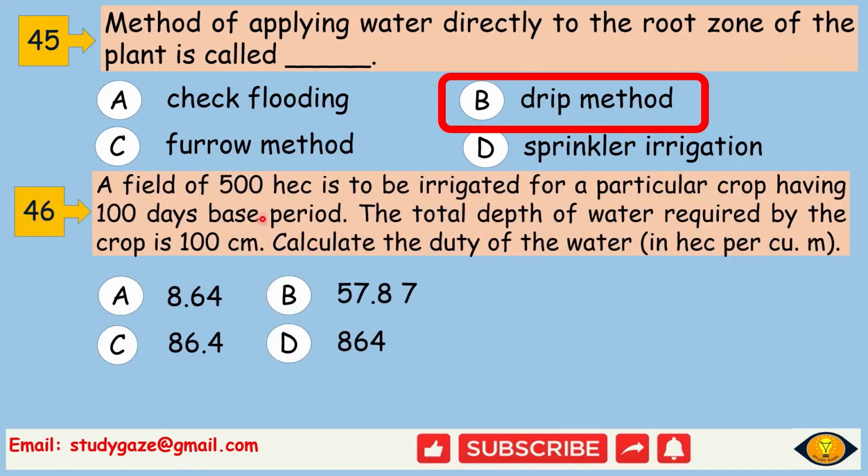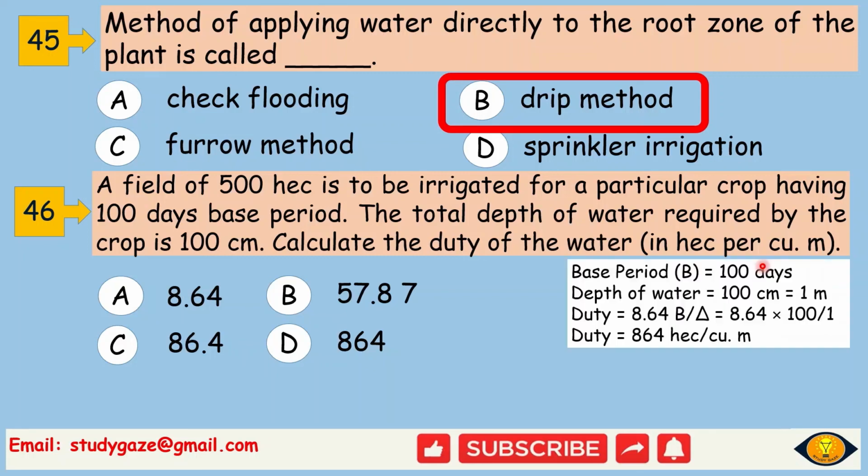A field of 500 hectare is to be irrigated for a particular crop having 100 days base period. The total depth of water required by the crop is 100 cm. Calculate the duty of the water in hectare per cubic meter. How will you solve this? You know, base period B equal to 100 days, depth of water delta equal to 100 cm equal to 1 meter, and duty we know is 8.64 B by delta. So 8.64 into 100 divided by 1, it will give you 864 hectare per cubic meter. So the answer is D.